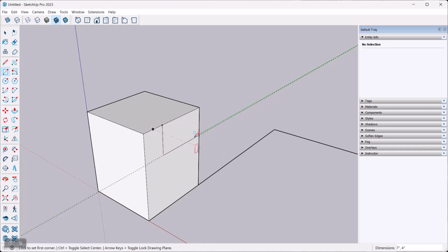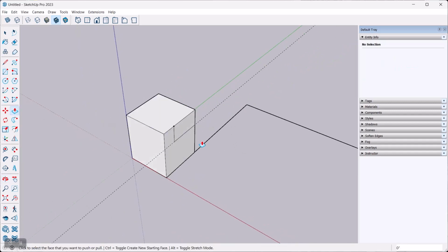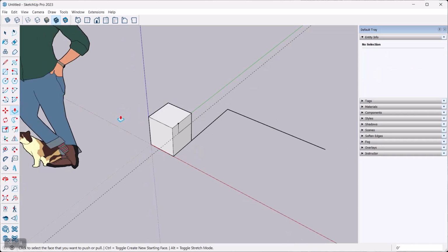And now I have these helpers that help me draw precisely with our regular tools, and then of course I can push, pull, and all of those kinds of things. So pick any of these, either direct distance entry, direct measurement entry, or some of these tape measure tools to give you temporary points. Very useful. You always want to be precise there.